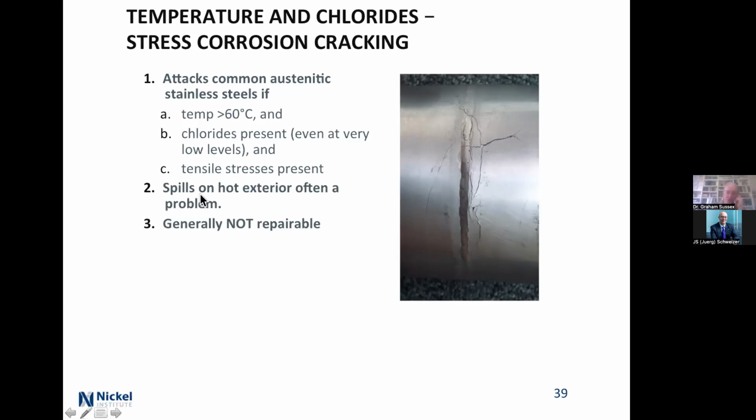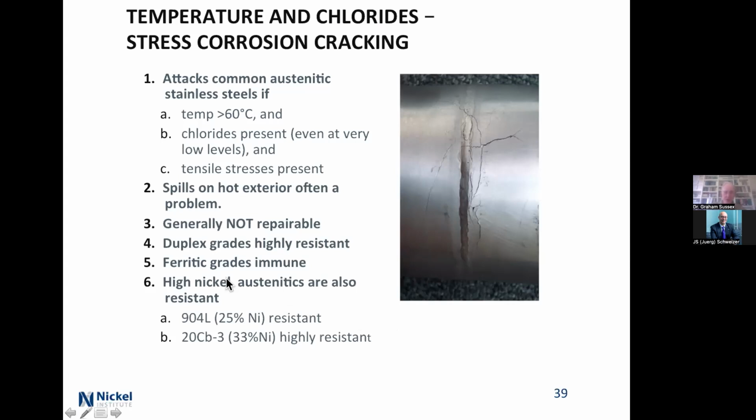How do you avoid it? If you've got water dripping on the outside of a hot water tank and it's got chlorides in it, then you can get cracking from the outside. And generally, you try and weld that up and the crack just keeps running away from you. Duplex grades are very resistant and ferritic grades just are immune. And the high nickels are really very resistant, 904L, 25% nickel. These are very resistant, but also a lot more expensive. Duplex grades are the usual things that people use.